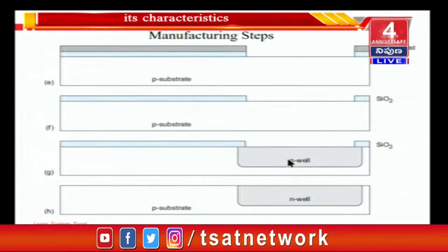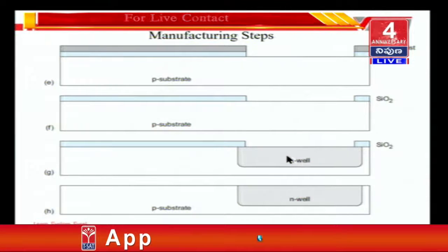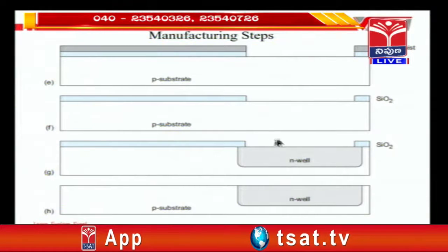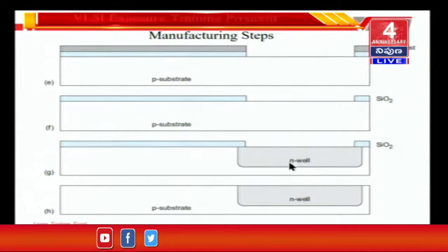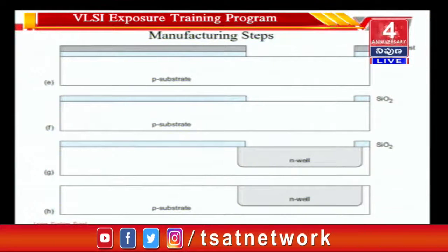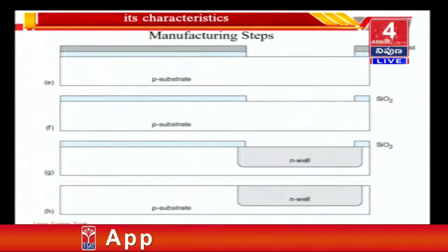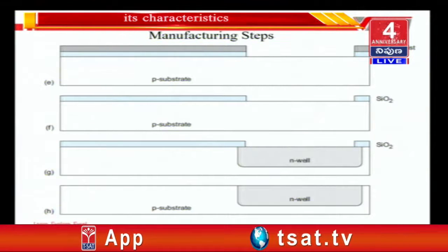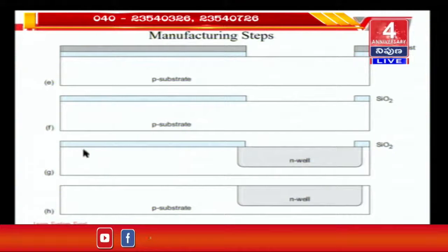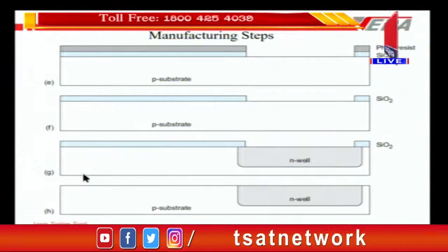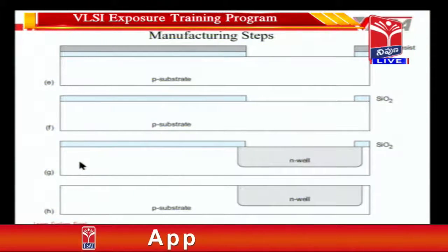The first few steps of manufacturing are basically to fabricate for the PMOS transistors. The N-wells, wherever they are required on the entire wafer, need to be made on the entire wafer with the objective of later on making PMOS transistors. So this N-well is done. The thickness of this wafer is typically 0.4 mm, or about 400 microns.